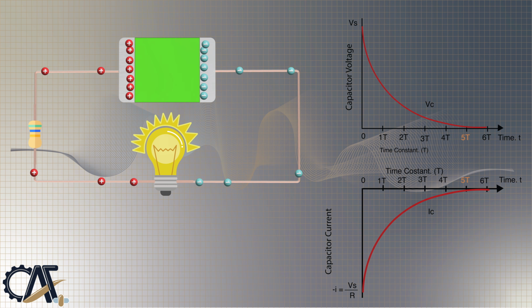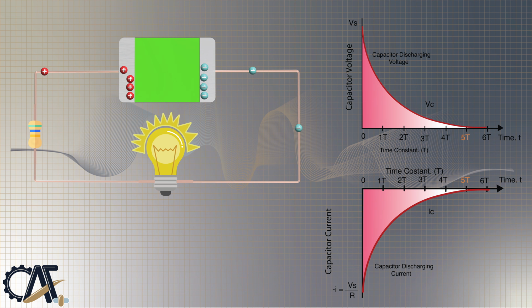Thus, if the capacitor is now connected to a resistance, like a bulb here, it can discharge again, and current is flowing back and keeping the light on, until the charge is completely depleted from the capacitor. Like charging, the rate of decay of the RC discharging curve is steeper at the beginning, because the discharging rate is fastest at the start, but then tapers off exponentially, as the capacitor loses charge at a slower rate. As the discharge continues, VC reduces, resulting in less discharging current.